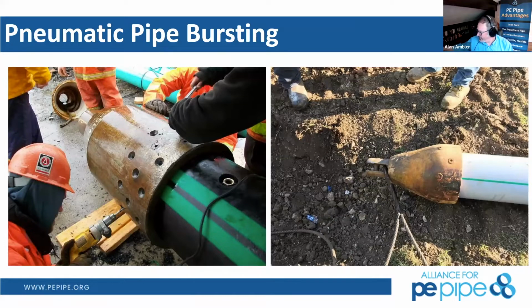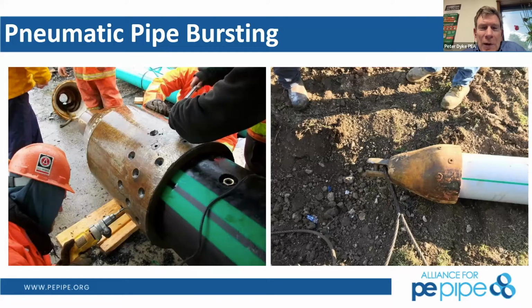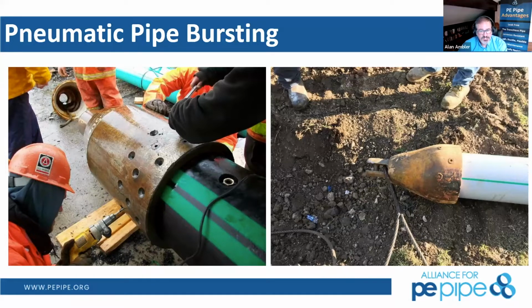Yes, Pete. One of the things when I was learning about this business, Alan, that I found confusing was they call it an expander head. And I always thought it related to the polyethylene, but it's not. It relates to the pipe that the polyethylene is being pulled through, because we're expanding that and fracturing that host pipe. So are we actually putting the bolts directly into the polyethylene? In this situation, absolutely. Yep. And it holds just fine. No issues. All of these heads slip right over top of it and everything holds into the polyethylene just fine.